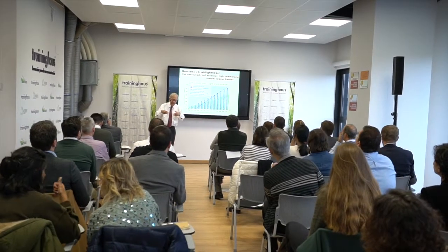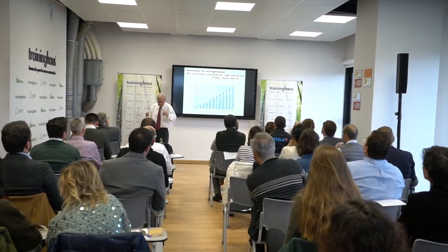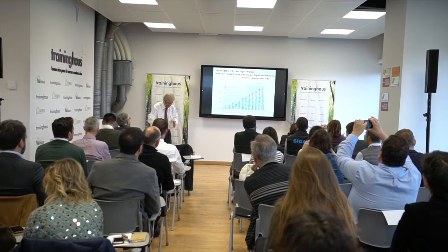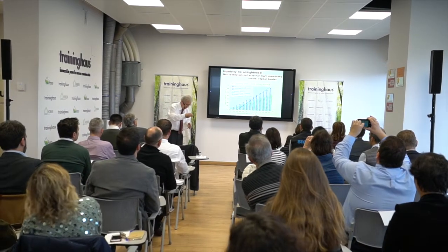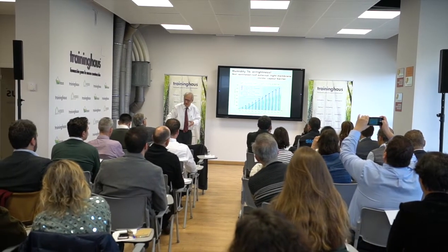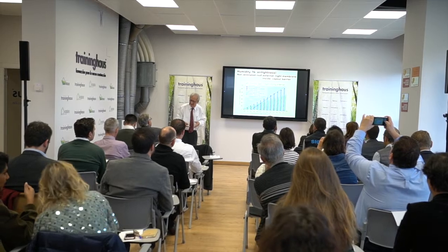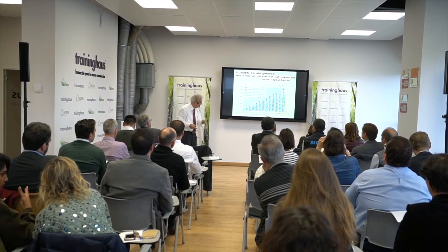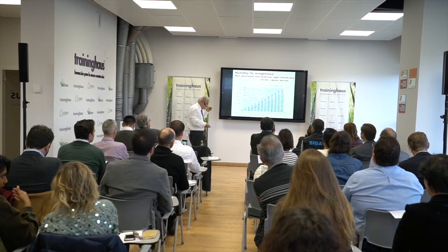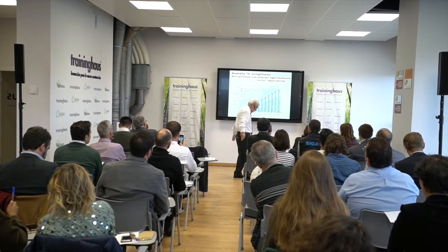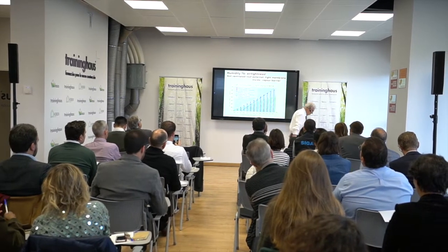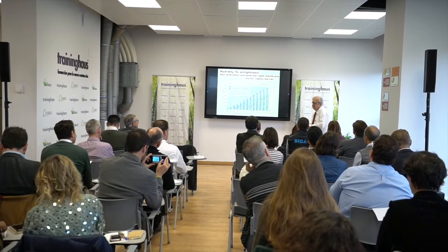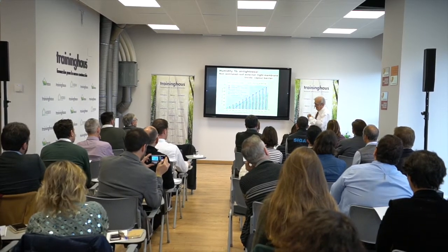What is sometimes confused by people is that they think that if you have an untight situation, if there is air going through, well, that would also help to dry it. And that's not true. This is what's easy to show. It's the forces driving the air through the construction. They are especially high during winter, and they are not very high during summer.